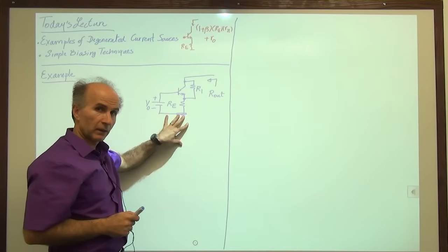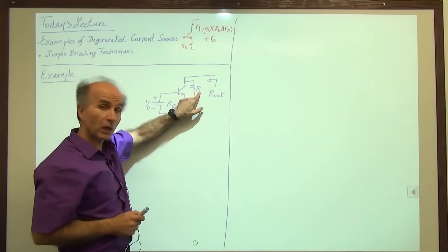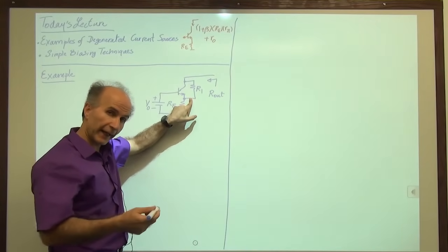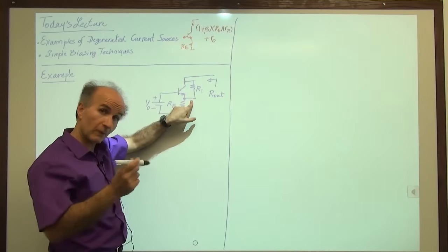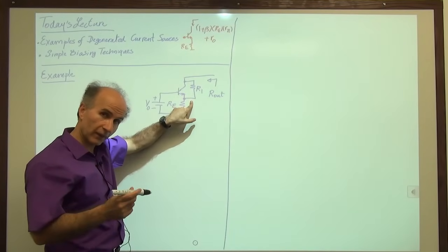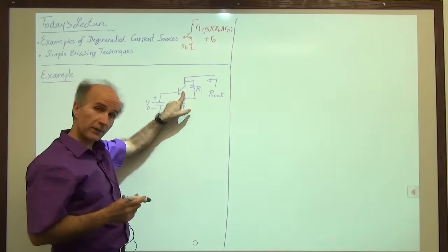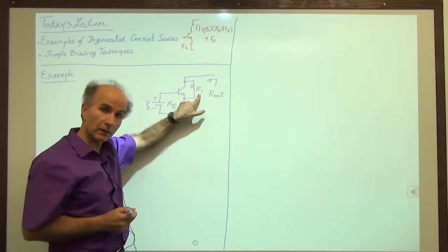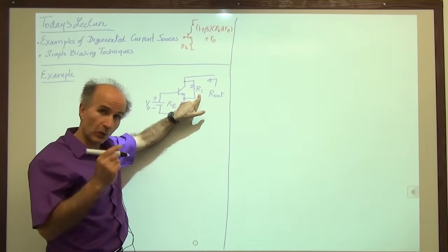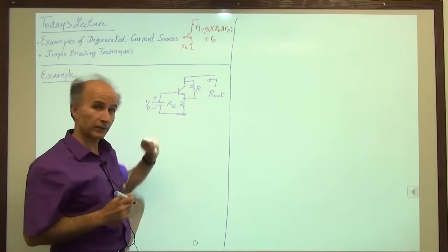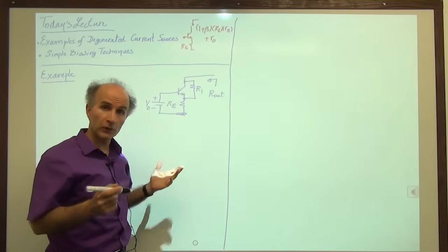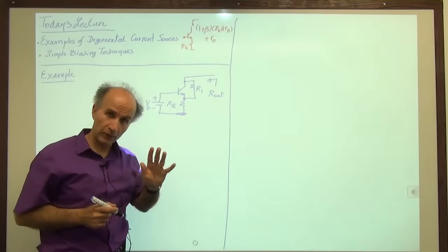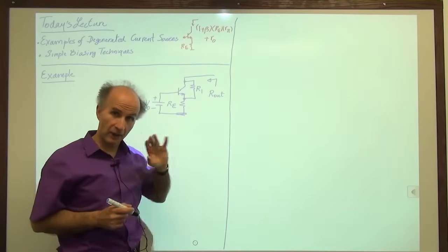So here we have a resistor called R1 from collector to emitter. So what we really have from collector to emitter in the small signal model consists of the RO of the transistor and this additional new resistor R1. And they are in parallel because they both go from the collector to emitter. So we don't really need to draw the small signal model of the circuit. But just to be sure, let's draw it quickly but not solve it.